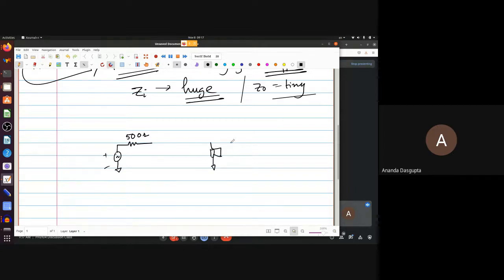And let's say a speaker itself has an input impedance of, say, 50 ohms. So that's the 50 ohms here. Now suppose you're going to join them together directly. Notice that your input signal, whatever that is, gets dropped across a series combination of a 500 ohm resistance, which is the microphone's own impedance, and 50 ohms here, which is the speaker's impedance.